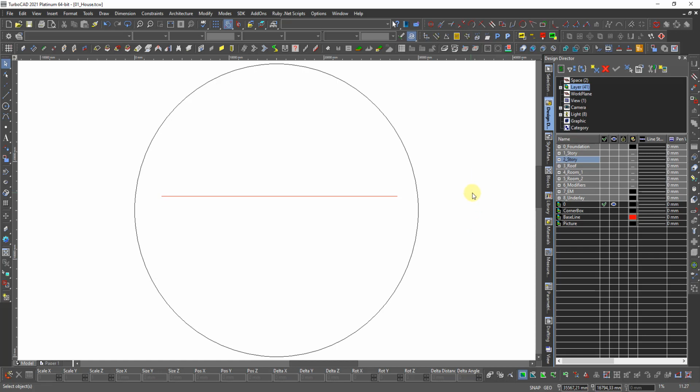There is also something named layer set that I do not use. The benefit of layer set is when you have made it, you can use it directly in paper space down here and say only what is inside that layer set is what we want to see. So that helps you make the view quicker. You don't need to check all the layers back and forth.